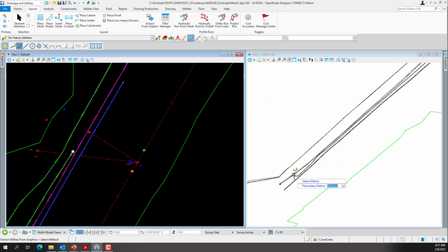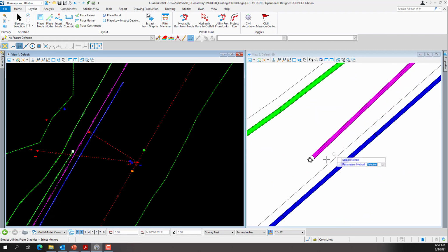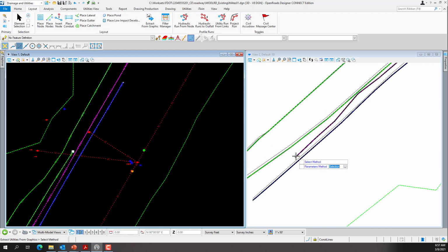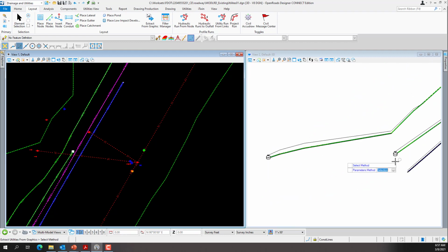It plotted that. You also notice in the 3D that it is pointing either caps or features on there on the default level. You would have to come back in and change these to nodes. So there's conduits, which are links, and nodes, which are the actual structures. So we would have to come back and fix the structure to put either a fire hydrant or a valve or something like that in there.